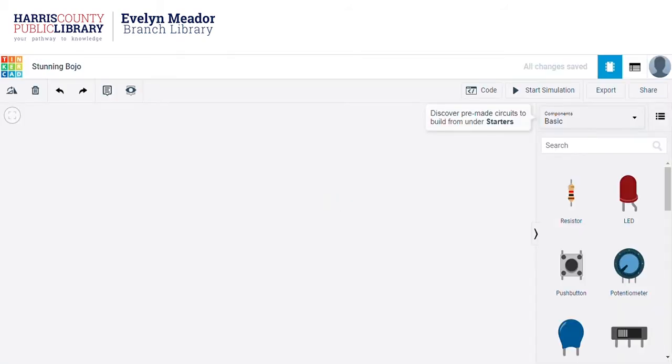The first thing that I want you to do is click up at the top here to rename your project. TinkerCAD gives it cute, funny names that they fill in themselves, but those names are just as useless as new project when you're trying to find which project this is. My suggestion for a name is Blink or Hello World, because this is the Hello World version for an Arduino. I'm going to call it Blink It, since I already have one that says Blink. Make sure to hit Enter to save your changes.